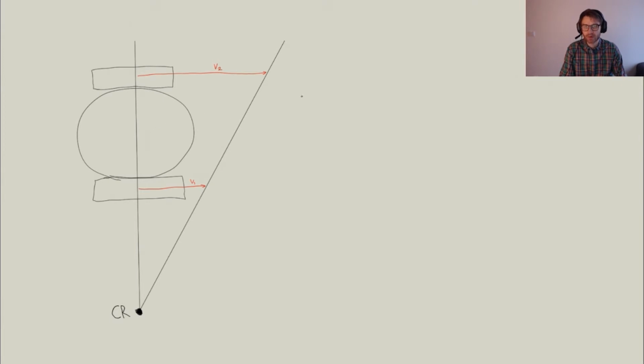So what we want to know is more than just the speeds at wheels 1 and 2. We would like to know the speed at which the Turtlebot is moving forward and what is the current turning angle over here. So now we want to know this theta and the average speed of the two wheels, this velocity here.